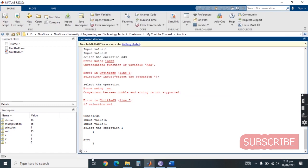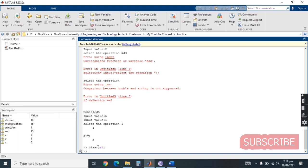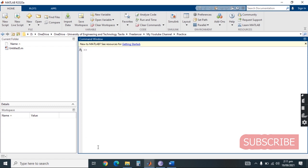Let's clear all memory first and also clear the command window by executing the following commands. That is clear all, which cleans up the whole memory of Matlab including the workspace window. CLC cleans up the command window only.